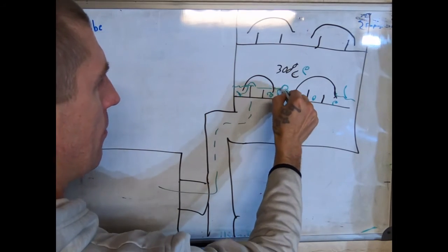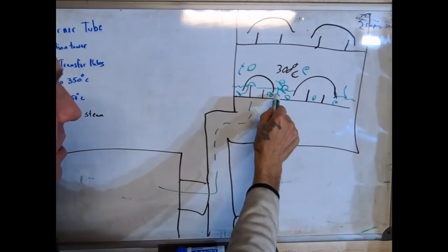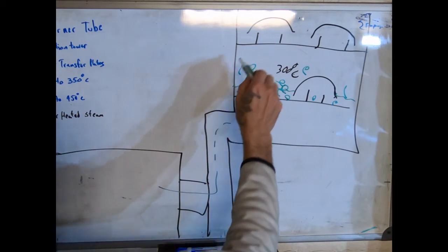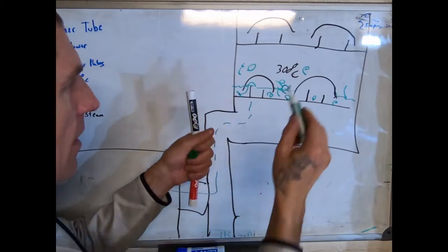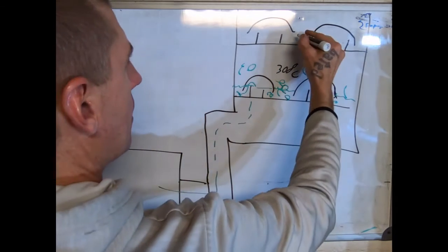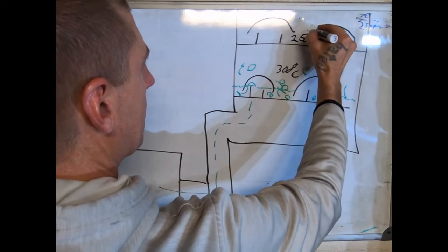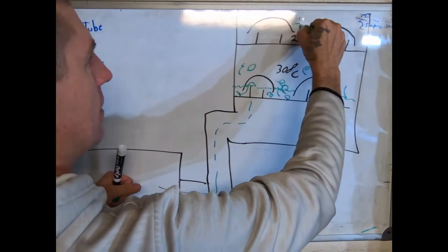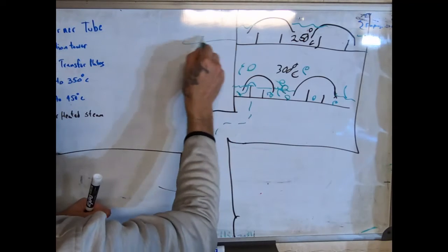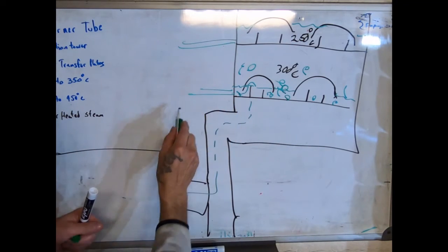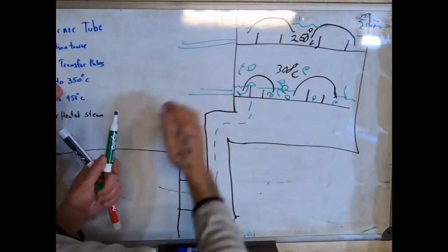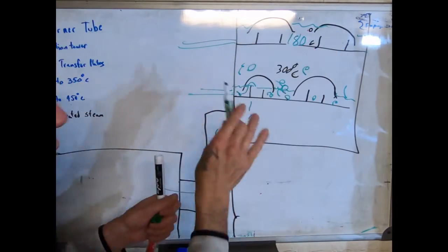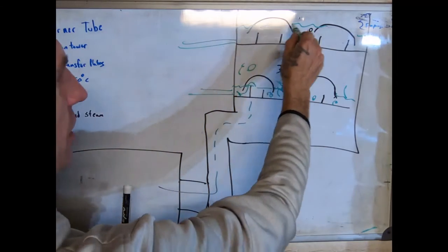So the bubbling gas comes out. This liquid here is 300 degrees Celsius now, but it's a very heavy oil. The next tower up may only be 250 Celsius. And it is a completely different substance. And you have tap tubes coming off the tower as you grow. Let's say we're at the top now, and we're at 180 Celsius, which is the lightest oil you get off this process. This is the good stuff.